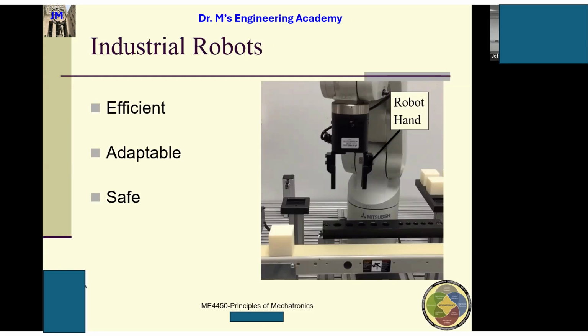You know CNC, right? Computer numerical control system. We have a CNC machine there, but we don't want to use CNC. We want to use these industrial robots to do some machining work for us. And what problem will you see? You will run into this: the robot is flexible enough, but it is not rigid enough. Because of these joints, right? They have waist joint, shoulder joint, elbow joint, maybe wrist joints, also finger joints. And if you ask this guy to close the hand to hold a machining tool, the rigidity is a problem. It's not rigid enough.